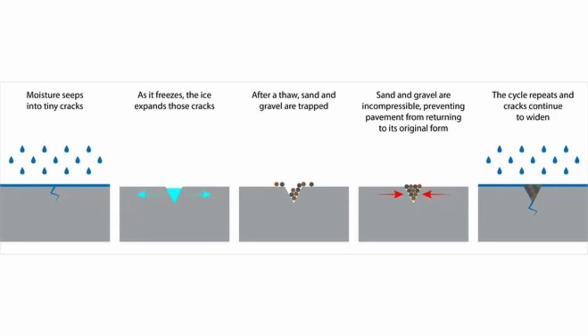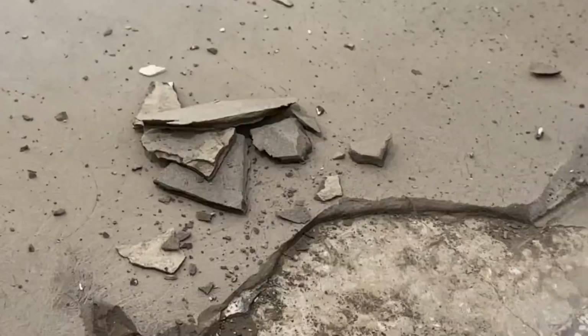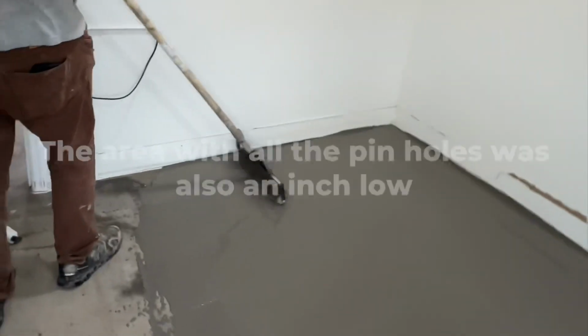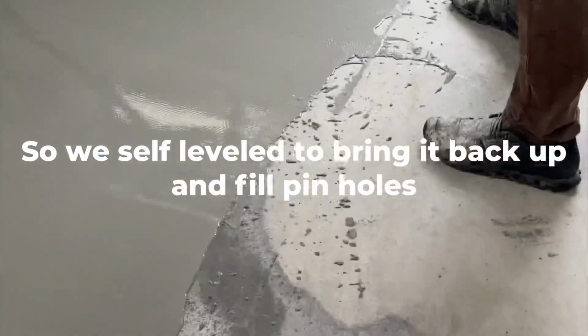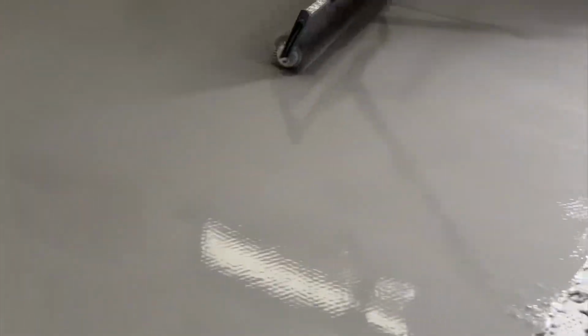Without air entrainment, water has no place to escape when exposed to freeze-thaw conditions. In the absence of air bubbles, the internal pressure from freezing water can lead to cracks and scaling in the concrete. When trying to achieve air-entrained mixes, application consideration is very important.